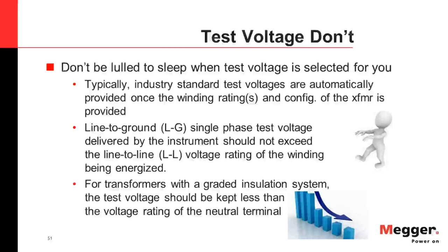Next, do remember that power factor tip-up may be a useful and revealing diagnostic. On oil paper insulation systems, power factor tests performed at all test voltages less than the maximum recommended one are expected to always yield the same power factor result. So in a power factor tip-up test, you're performing an additional power factor measurement at a different test voltage, and the two power factor measurement results are compared.